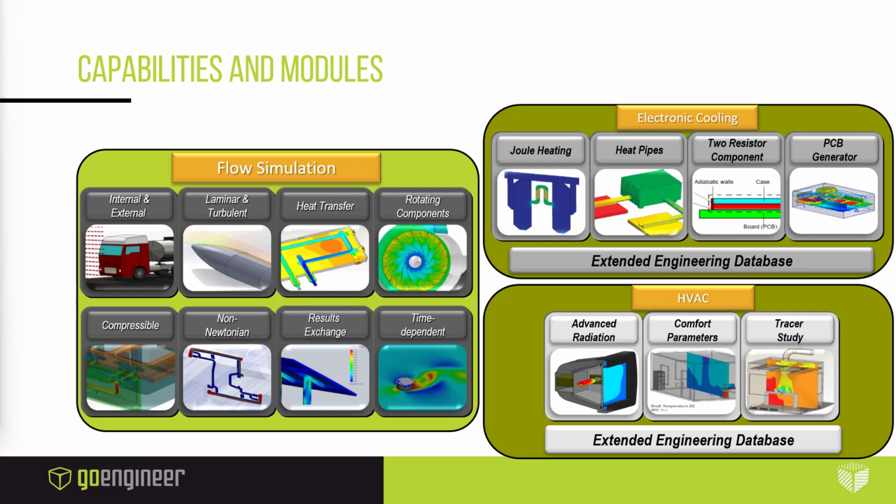You'll be able to simulate fluid interaction within pipes and valves or pumps, as well as investigate the aerodynamics of your designs by influencing the environment around the exterior of the designs, like in a wind tunnel situation. Also, as mentioned in the previous slide here, we're able to model heat transfer. So all three mechanisms of heat transfer can be considered: conduction, convection, and radiation. In addition, forced or natural convection models are also available.